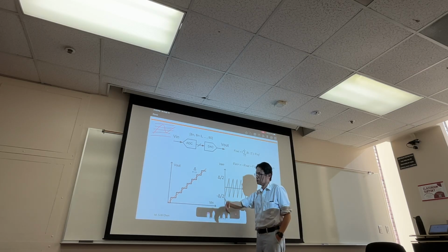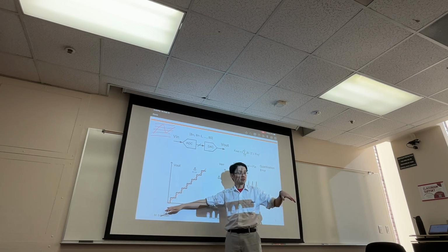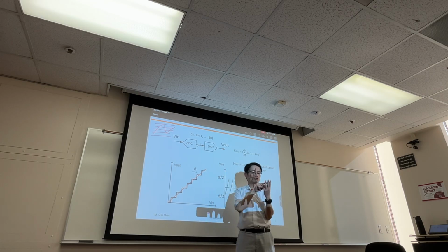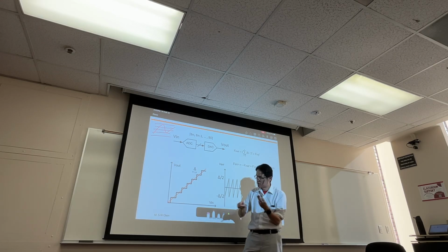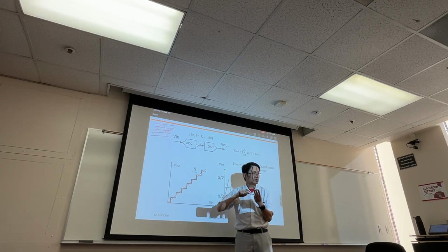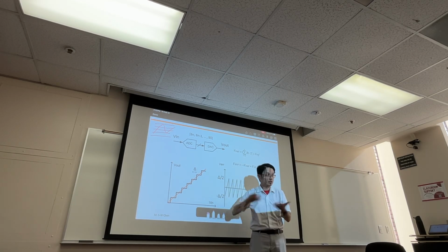Digital bits. So let's say this is the smallest level. Usually you use the smallest digital code. So let's say if I do a 3-bit, what's the smallest code? 0, 0, 0. What's the next code that I can represent? 0, 0, 1. That's exactly what the ADC is trying to do.